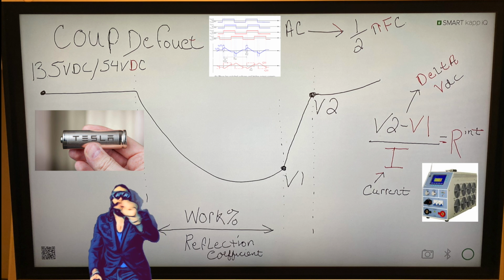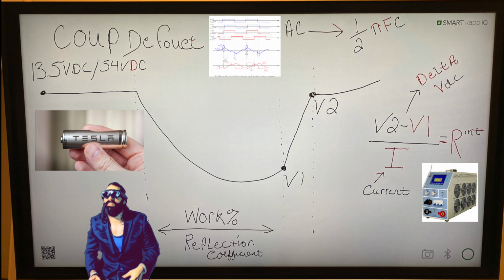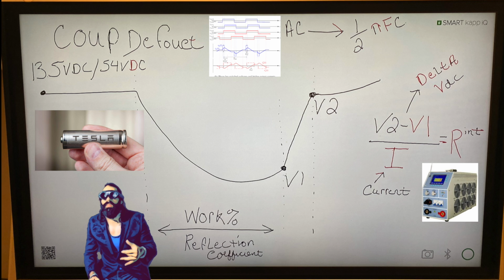Now the noise floor is 5 amps, but the signal you're injecting with those small meters is 1 amp. So what happens to the resolution? It disappears. It gets lost in translation, and that's really important to understand because depending on these systems, especially older systems, noisier systems, it's not going to effectively find a defective battery in time.